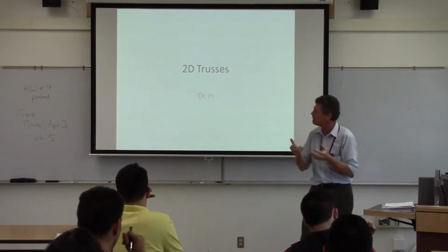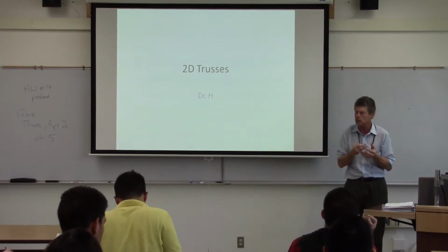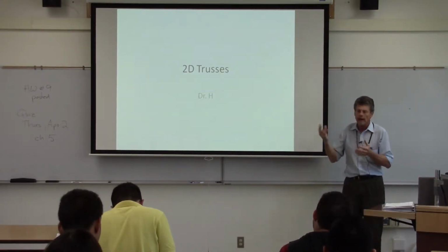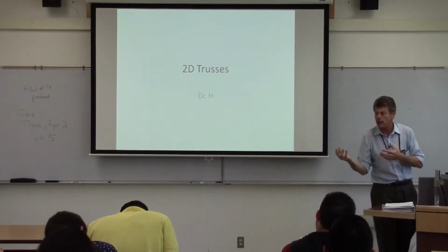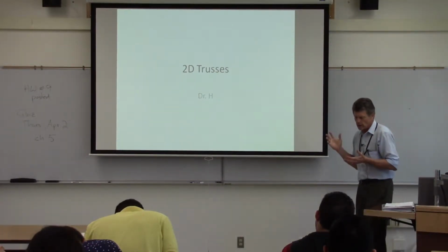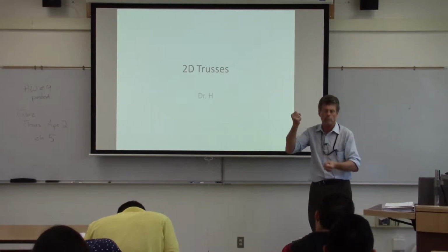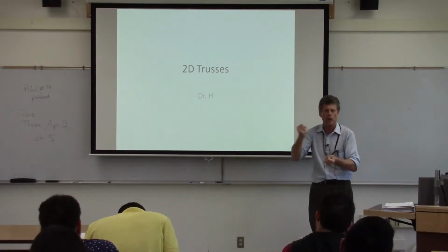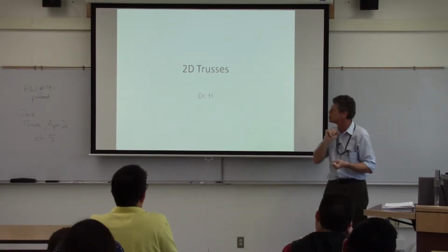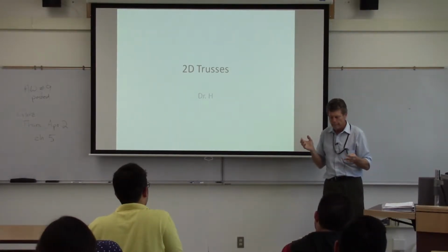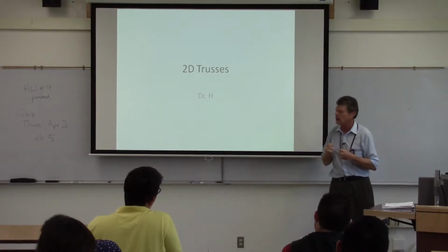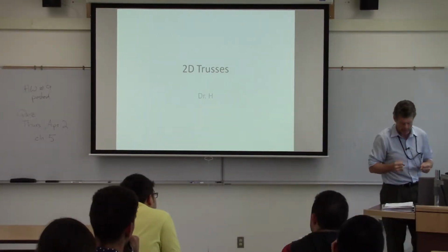We're going to be able to look at what's going on internally in a structure, in a particular element, and get an idea: okay, I need to size that bigger or smaller. Is it in compression? If you have a truss element in compression, you have to worry not so much about crushing, but buckling. That'll be a whole separate issue you get into in junior, senior year. Tension, then you need to make sure you have enough area so the thing doesn't snap.